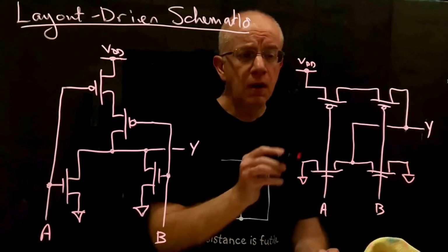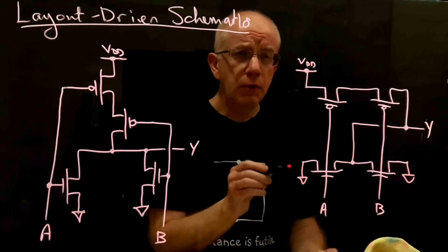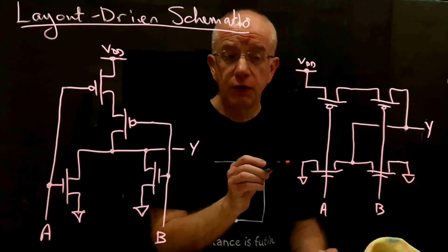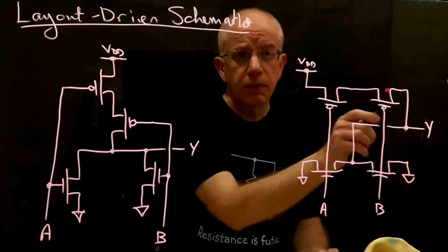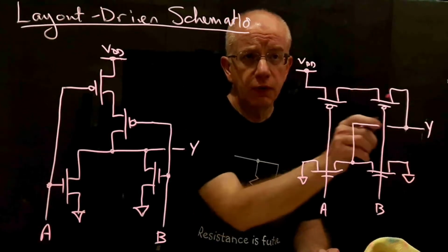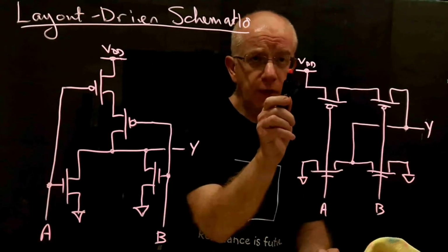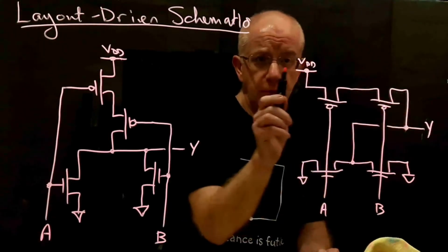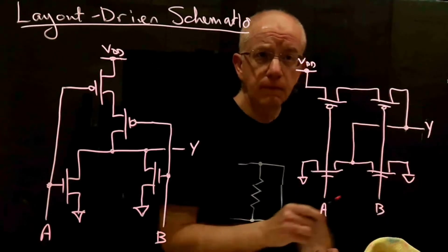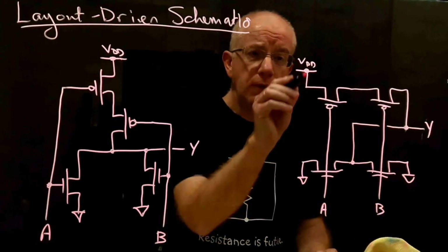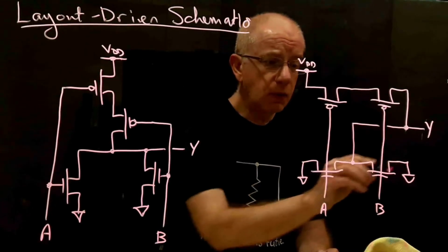Okay, so you remember the way we talked about organizing the digital layout was so that the transistors ran in strips, like the diffusions or the active regions ran horizontally in strips parallel to, let's say, a VDD rail, which you could imagine extending this little symbol out here, and a ground rail down here. And so we can tap off or tie up to the VDD rail where we need to. We can tap off to the ground rail where we need to.